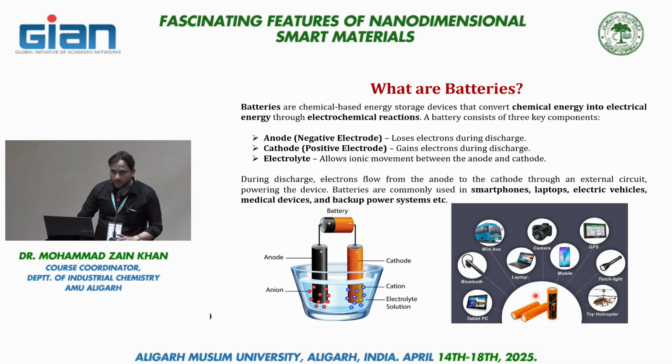The lithium ion battery which is being used nowadays can provide stable power. It can be used for a long period of time. It has very good charging and discharging capacity. You can use it for years. The only issue with the lithium ion battery is overheating and the energy density. The main thing is overheating. It heats up during the process, and some method has to be devised to control its excessive heat, to absorb its heat so that the temperature is kept normal.